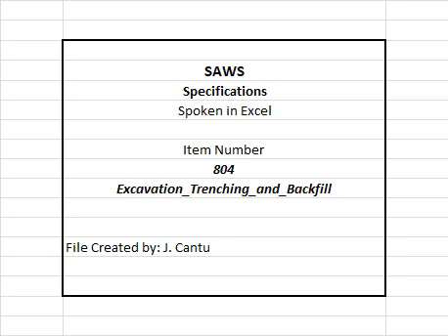G. The practice of undercutting at the bottom or flaring at the top will not be permitted except where it is justified for safety or at the engineer's and/or inspector's direction. H. In special cases, where trench flaring is required, the trench walls shall remain vertical to a depth of at least 1 foot above the top of the pipe. I. The trench bottom shall be square or slightly curved to the shape of the trenching machine cutters. J. The trench shall be accurately graded along its entire length to provide uniform bearing and support for each section of pipe installed upon the bedding material.